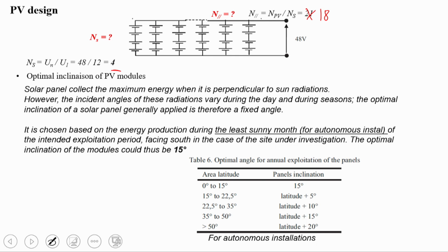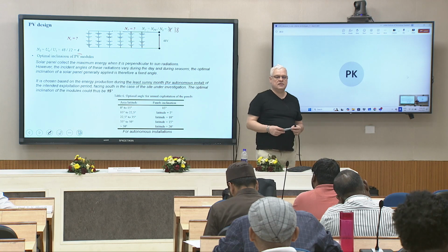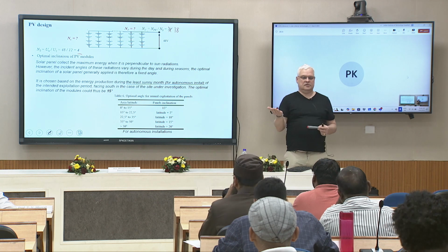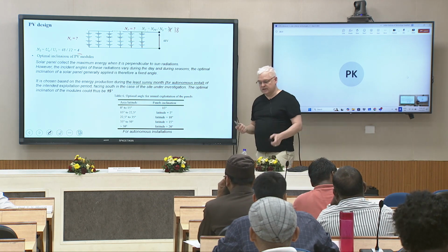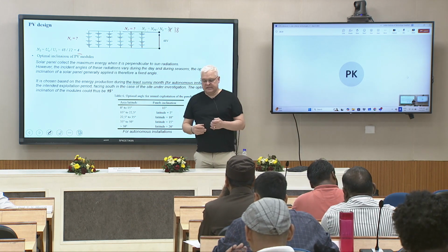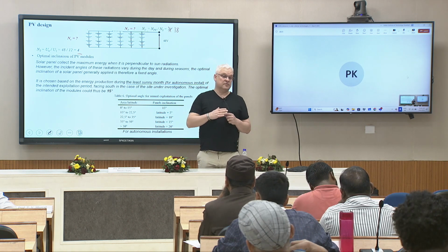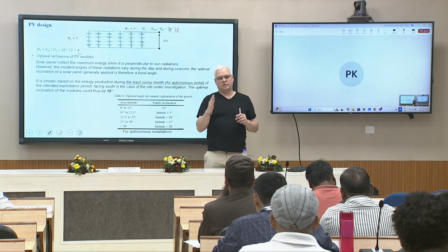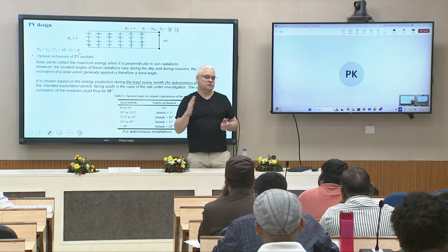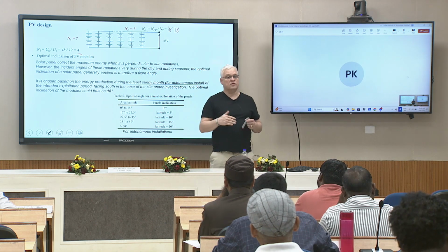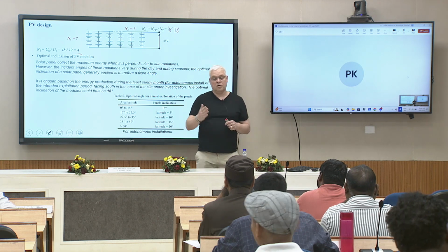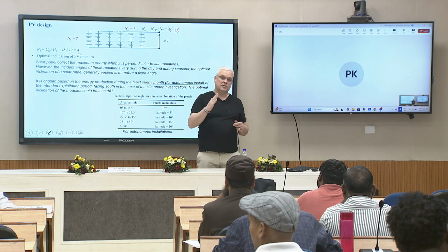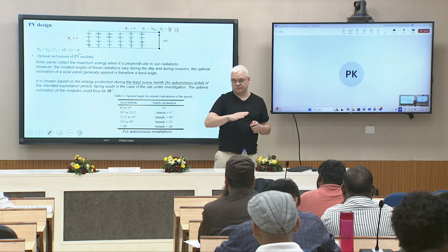You also have a rough idea of the inclination of the panels depending on the latitude. The best inclination obviously depends on the latitude. The higher the latitude, the more the panels go toward the vertical. The lower the latitude, the more the panels go near the horizontal.